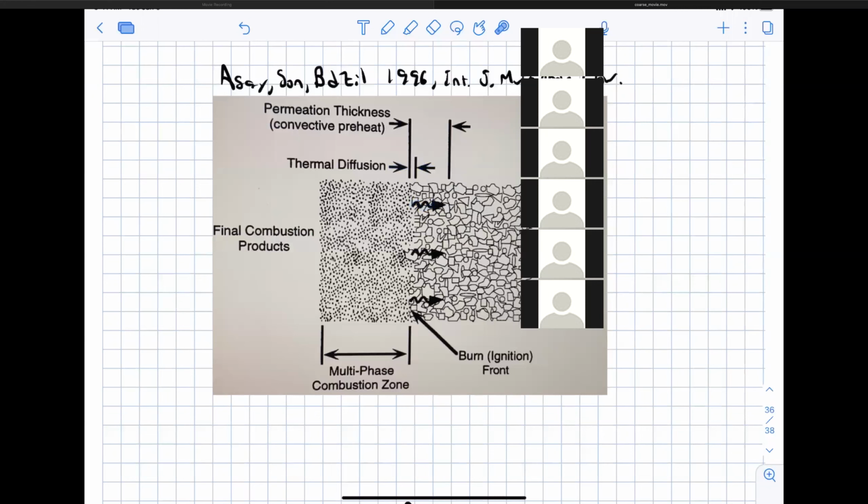And again, they're not even drawing all of it. Due to the burning at the surface here, some of the particles get ejected, and then you have big chunks of burning stuff that come off of the surface of the porous bed. And that's called deconsolidation burning. That also adds quite a bit. And so this phenomenon of convective burning becomes very, very complex and very situation specific.